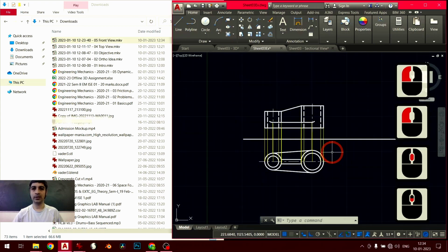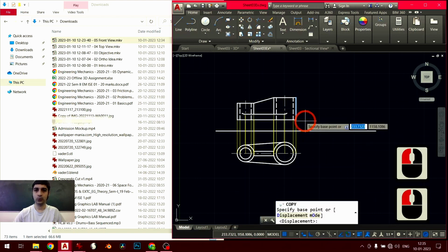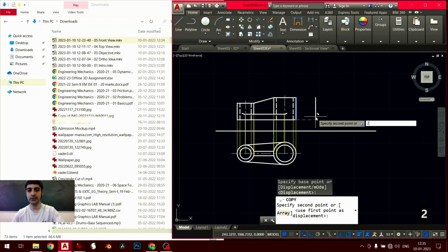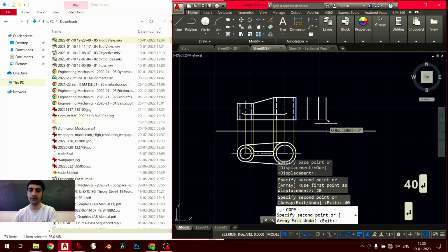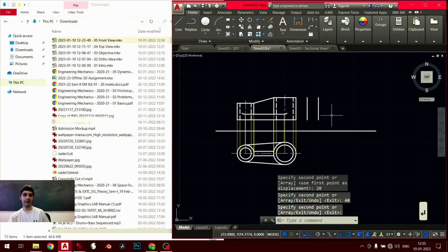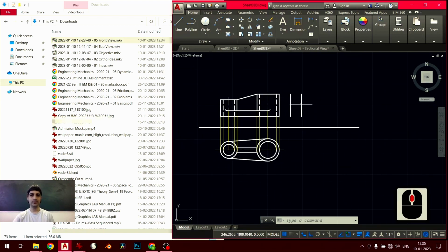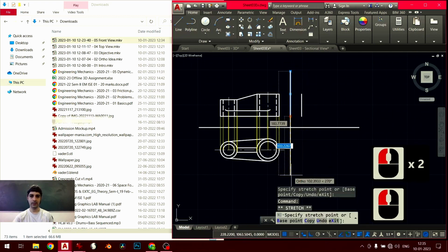Okay, next we'll start working on the side view of this object, before which I'll make a copy of this edge to the right by the same distance as between the front and top and the XX lines. So that's 20 units for the vertical YY separator, and then 20 units beyond that for the leftmost edge of the left hand side. You'll notice that I'm constructing the left hand view on the right of this front view because that's what our orthographic conventions are for the first angle method of projection. So this becomes the leftmost edge. Now we can construct this view without doing any projections work, but I'll be doing the projection work beforehand anyway, so that I don't have to worry about it later.